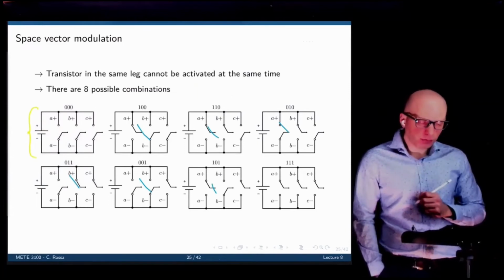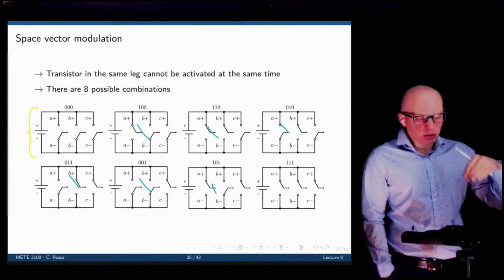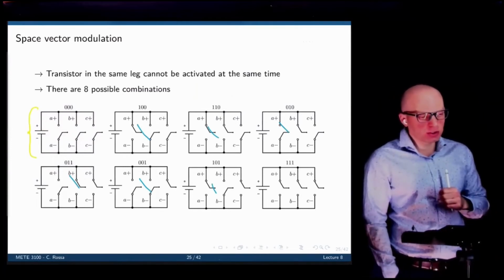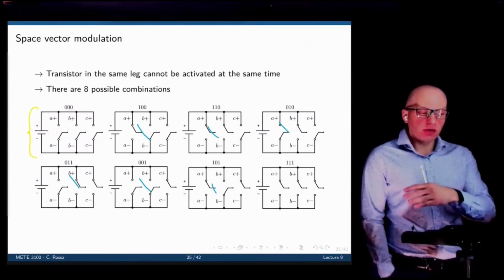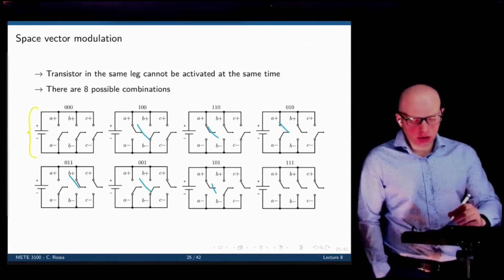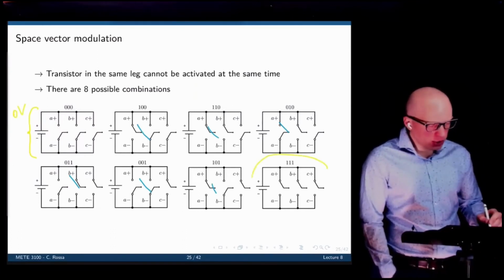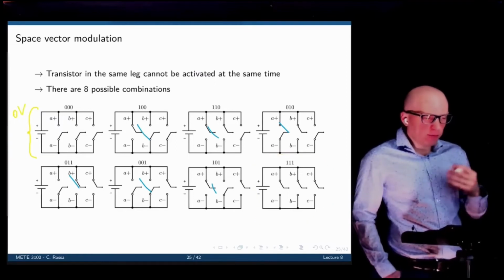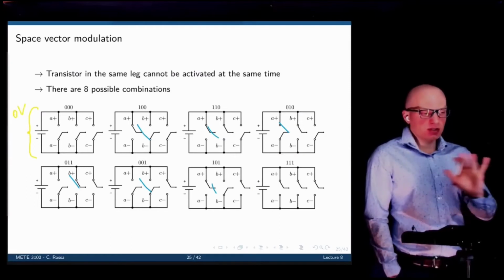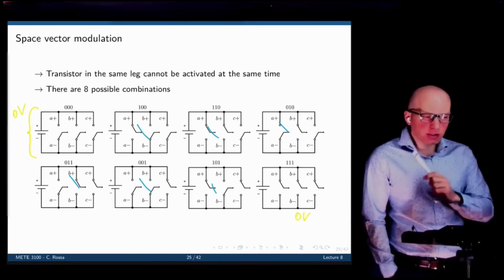This one, where all transistors are switched to the low potential. So what is the voltage across the load in this case? Everything has the same potential, right? So the effective voltage drop across the load is zero, and that also happens when you switch everything to the high side of the voltage. The voltage on either side of the load is the same, so the voltage drop across the load is also 0 volts. Now you're starting to get it.